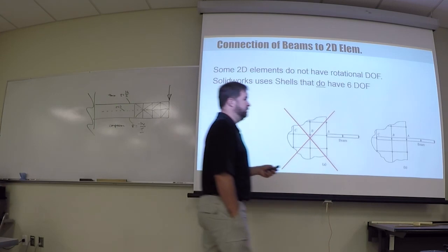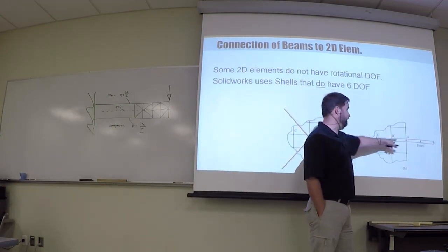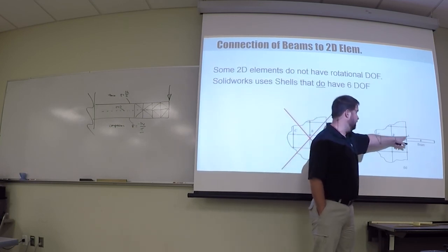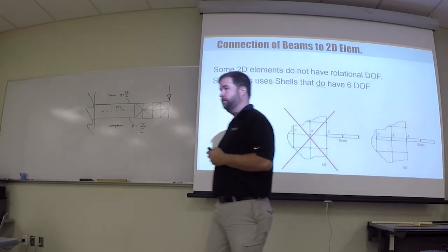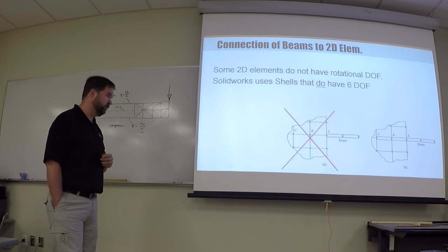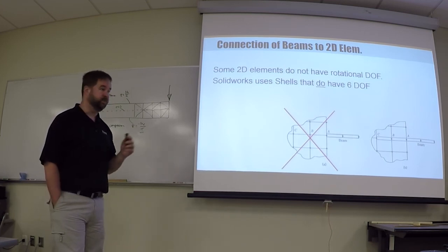So then there's ways to avoid that. So in this case, I could model this with my beams going back into the structure, which would then create that moment here so that the structure works. Okay? That's kind of an unlikely scenario, but I wanted to mention it in case you come up with some weird stuff out of your results.